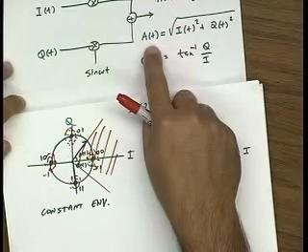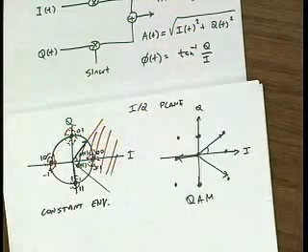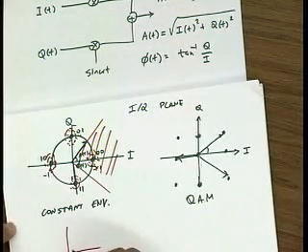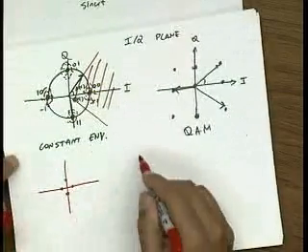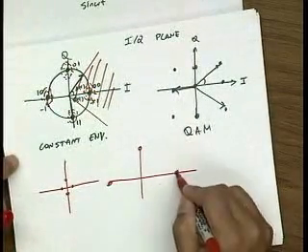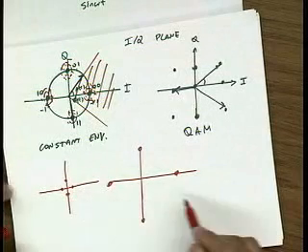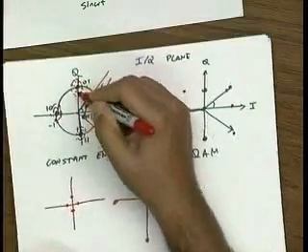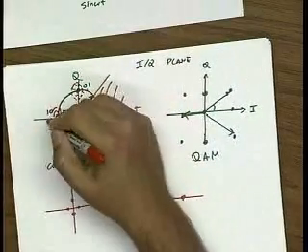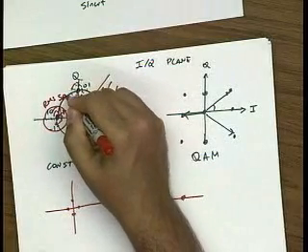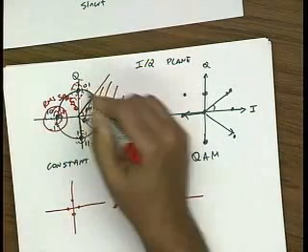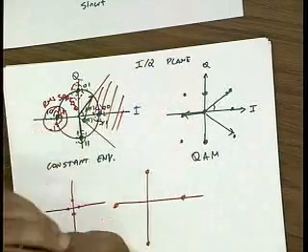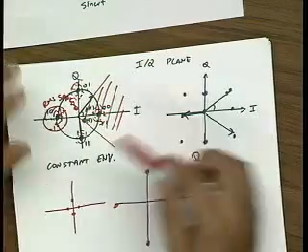So if I wanted to reduce the probability of error, I would basically scale this. I would send A of t, which is bigger. In other words, if this were the original constellation, I would do much better to send this constellation, right? Because now the probability of error is much smaller. And of course, the amount of spread, the RMS value of the spread here, is related to the amount of noise in the channel. And so you can see that signal-to-noise ratio plays a big role in determining when you make an error.